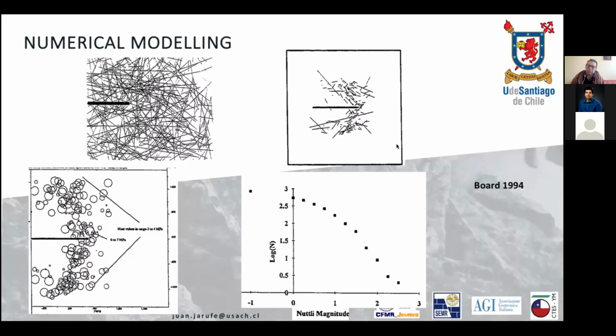So he was simulating the fractures of the rock, and then he put in an excavation. The excavation induces stresses, and those stresses make those predefined fractures shear. And each fracture, when it was sheared, generated a seismic event, as those there. And based on those events, he could build a frequency magnitude distribution.